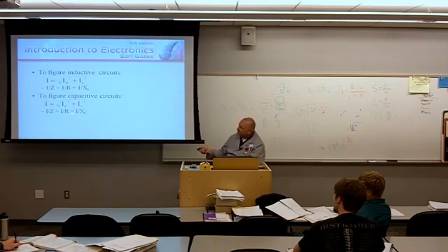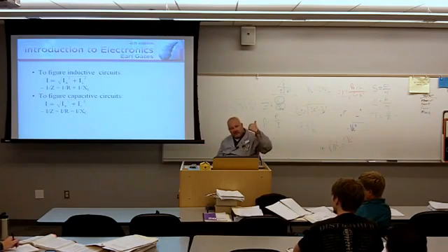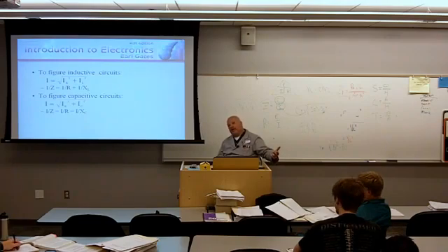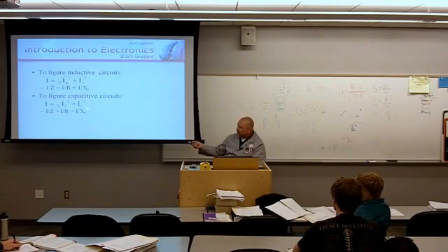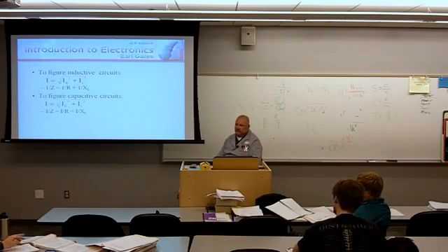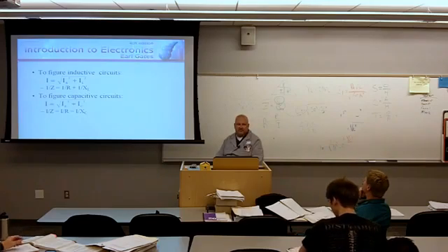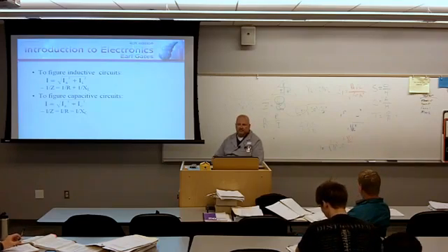What kind of a circuit is this? AC, parallel, RC circuit. How do I know that? Because I'm taking the vectoral sum of the current through the resistor and the current through the capacitor. If this were a series circuit, they're the same. Current's constant in a series circuit. Make sense?